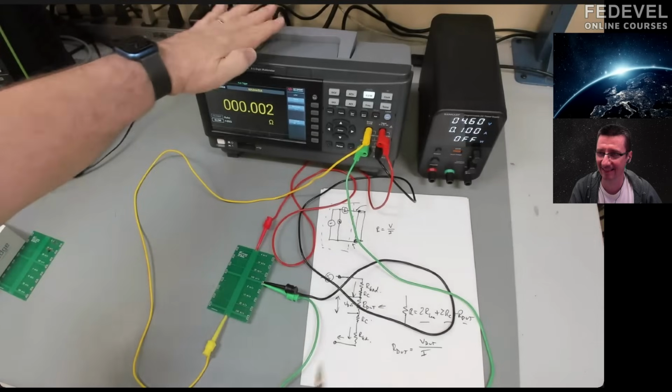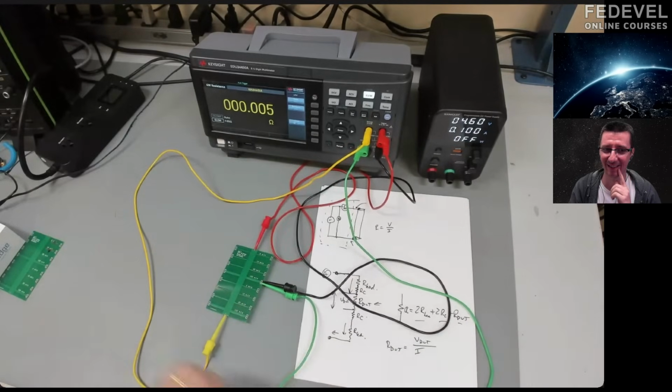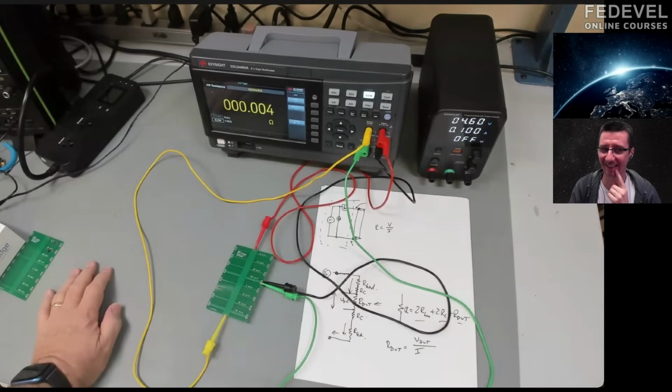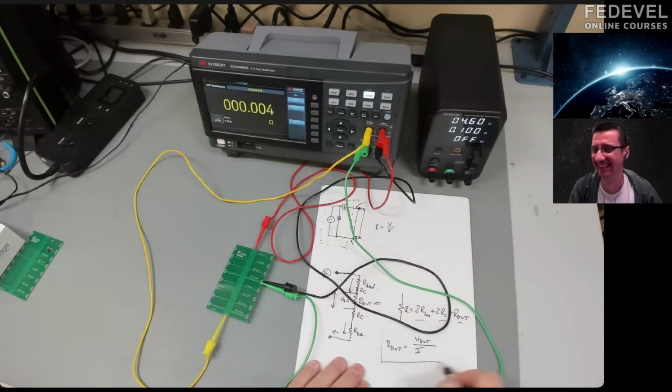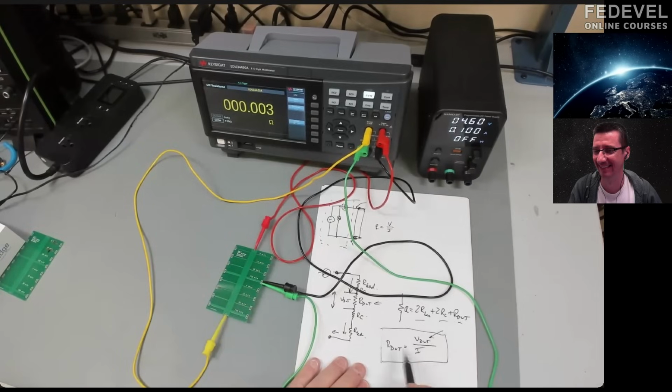We're going to do exactly the same thing that this guy does. I'm going to guess. Can I guess? Yeah. Are we going to put there more current? I don't know. You bet. Exactly right. Because here is the relationship. This tells us how we're going to do the measurement. If we want to measure a really small resistance here, we have to be able to measure a really small voltage and generate high current. And so the way we measure the low resistance is we send in large current and we measure small voltages.